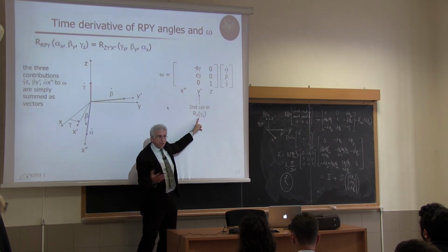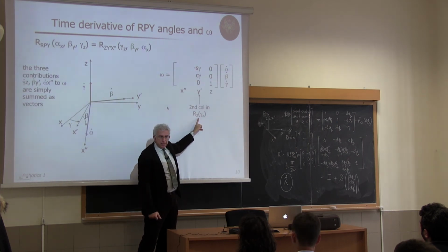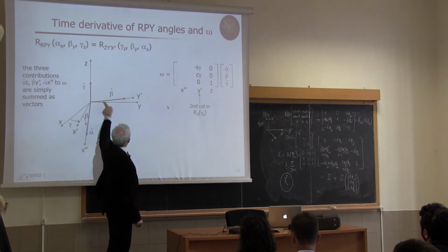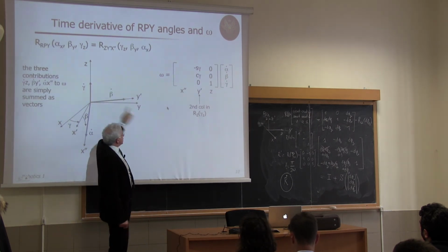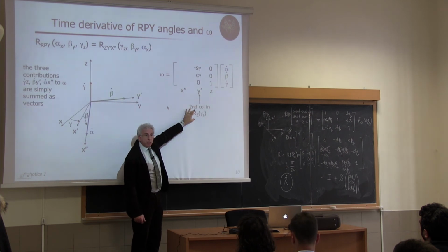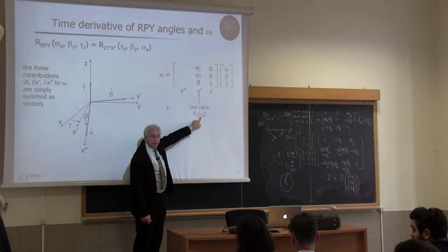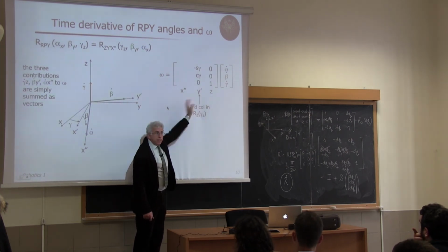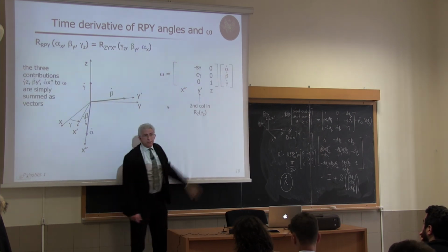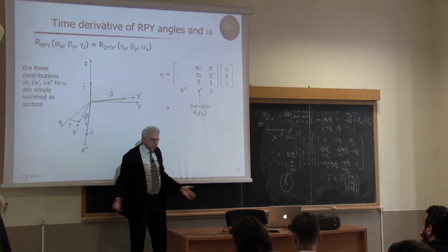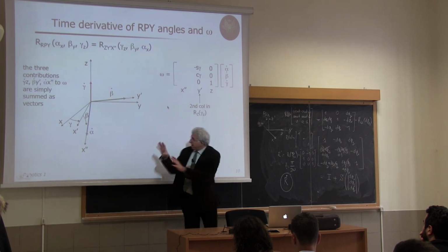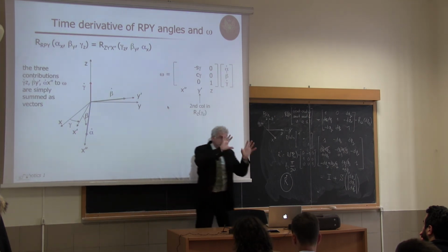The directional cosine of the y-axis after the rotation. So you just build the elementary rotation matrix RZ with gamma, take the second column, and this will be it. So this is algorithmic. Here it requires looking at the geometry, trigonometry, and so on.